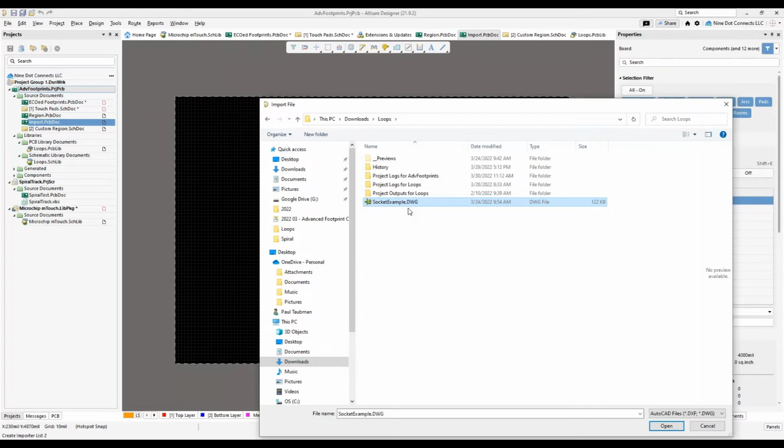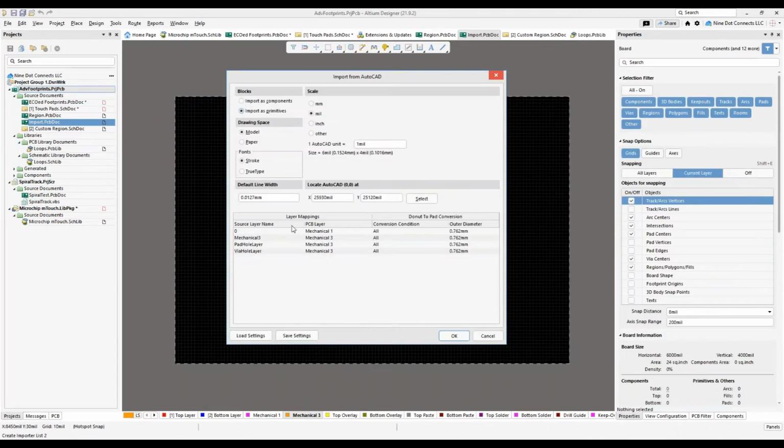The thing is that it was created back in the 1980s, in a time where memory management was really important. It is very cryptic to read. You do have to have some type of cipher in order to understand what the numbers are in there. And one of the biggest issues with DXF DWG is that they created their own coordinate system, on purpose, because they didn't want to be tied to either metric or imperial. I'm glad they did it, but at the same time it causes a little bit of confusion, and that's why I think a lot of us get a little bit wound up when we start going into this.